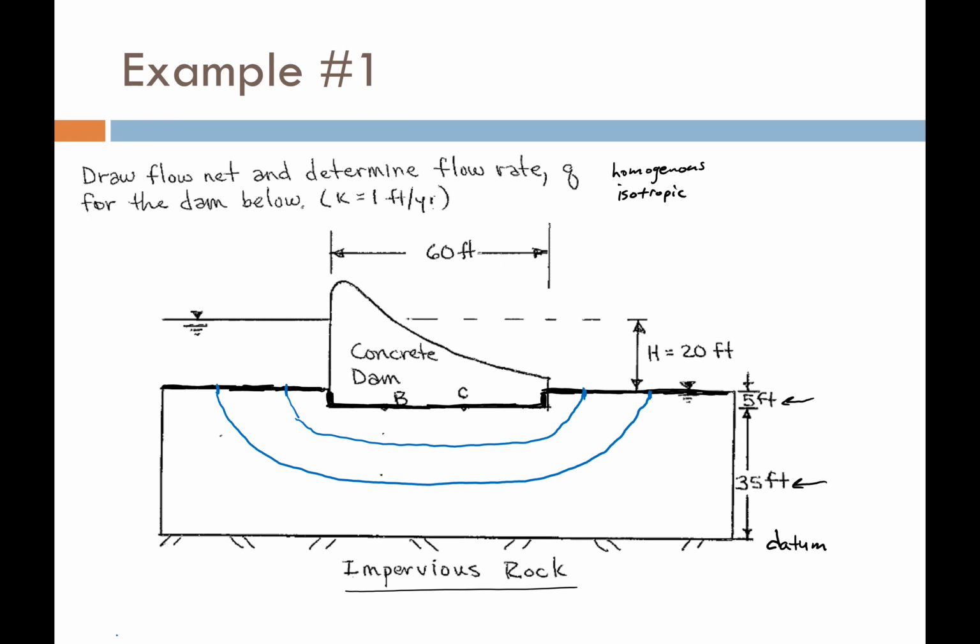Okay, so now I'm going to switch my pen to maybe red. That should show up well for the equipotential lines. So now, again, remember, I'm looking for nice square elements. So I've got to start here, maybe on the corner, and I'm going to come down, and I'm going to try to cross these flow lines at as close to 90 degrees as I can get.